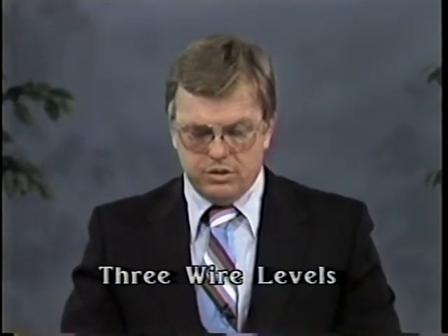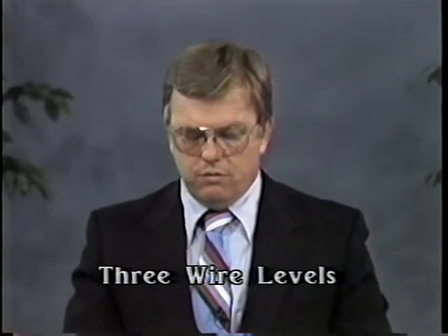This procedure is repeated until the last elevation of 412.005 for the closing bench is checked against the known elevation for the point of 412.011. This comparison tells us the level run does not close on the known elevation for the benchmark by a difference of 0.006 of a foot. This error is distributed throughout the level loop to close the elevation run on the bench with a difference of 0. Our next example of level notes illustrates differential level notes for 3-wire levels using a foot rod.